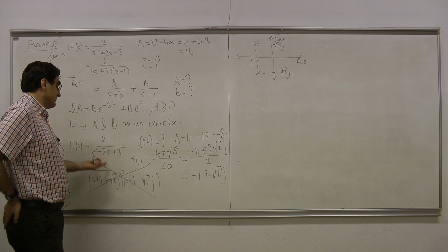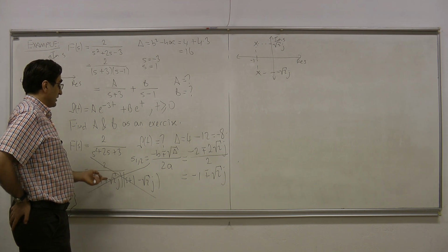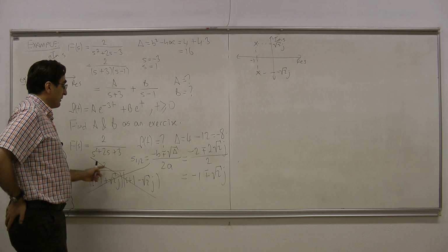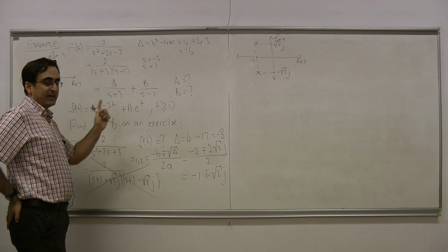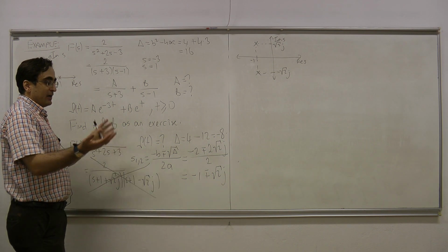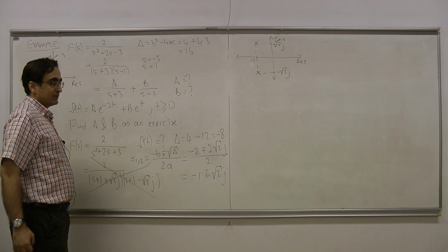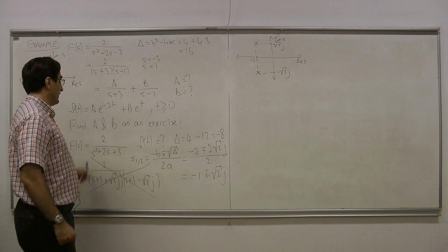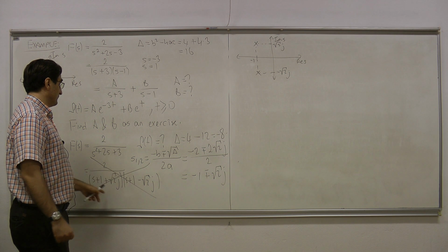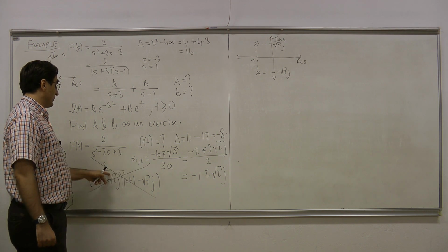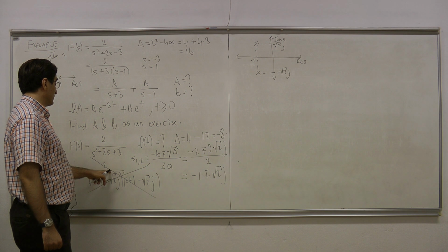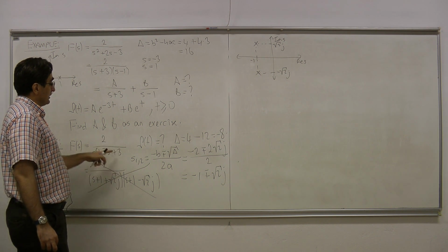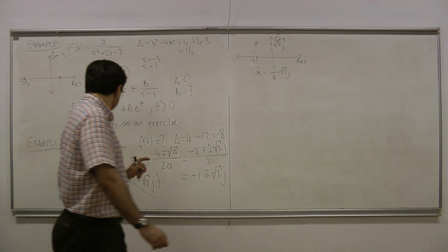This is a valid way to take the inverse Laplace transformation, applying a partial fraction expansion to such a term. But then you're going to get complex a and b factors, and at the end, those a and b factors, their complex parts are going to cancel, but you will probably make a calculation mistake if you try to do it by applying partial fraction expansion to such a term like this. So instead, using this polynomial directly here is easier.